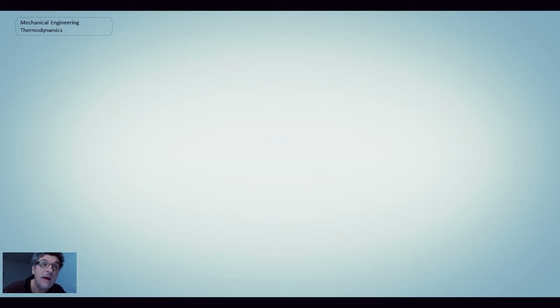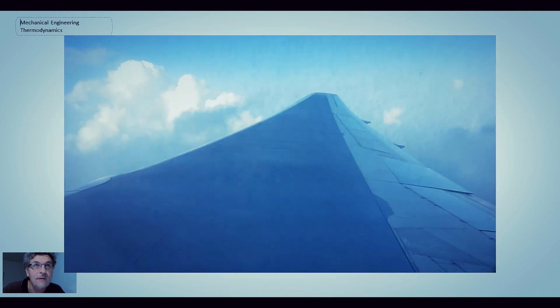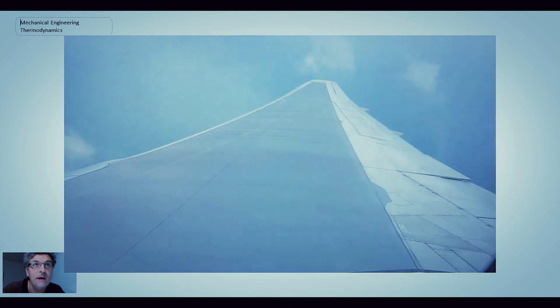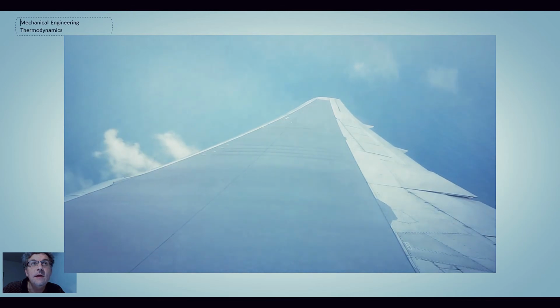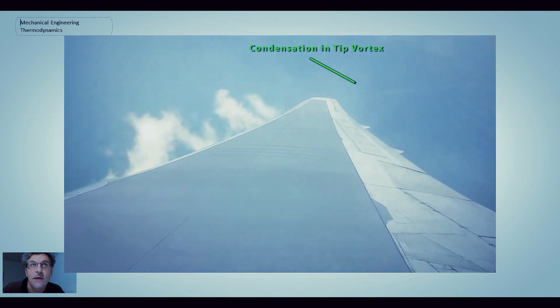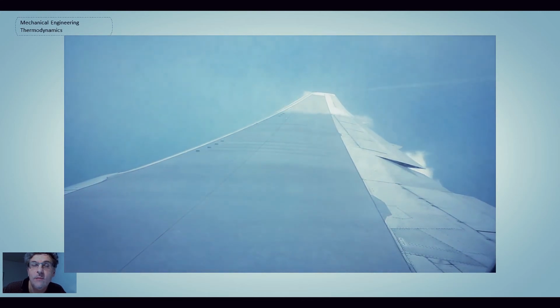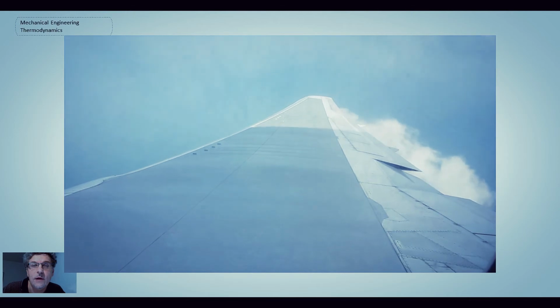Quite often these processes don't occur naturally, and they're often induced by human activity. So what we have here is a recent flight on a 767 into Tokyo, Narita Airport. But what you can see is on the wingtip, watch there, you'll start to see white formation coming off in the wingtip vortex. That is because you have a very low pressure coming off the wingtip vortex.